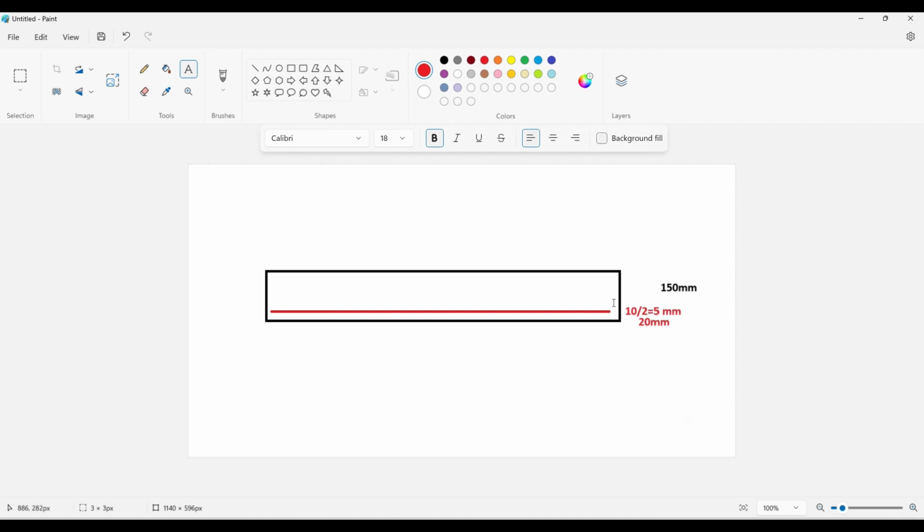Okay, so what I'm doing is, whatever is the left, this distance of my slab. What is this distance of my slab? It is basically 150 minus the clear cover minus d by 2. I'll get something like 125 mm as my effective depth. Okay, 150 is total depth, 125 is effective depth. So I'll get 125 mm from where? From basically this point to this point.